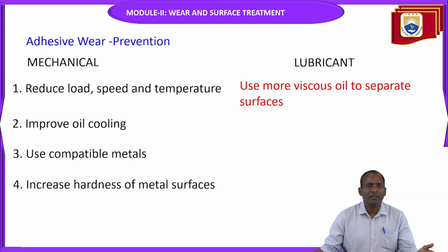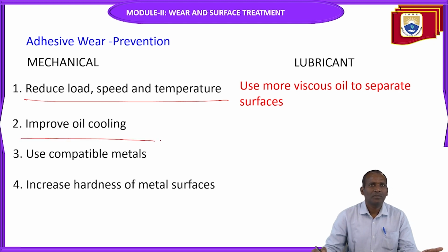For this wear, mechanically you can reduce load, speed and temperature. You can minimize the adhesive wear. Don't apply extreme load. Don't apply extreme speed. Similarly, temperature: improve oil cooling. Use proper lubricants. Use compatible metals. Don't use other metals.